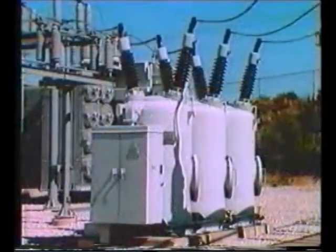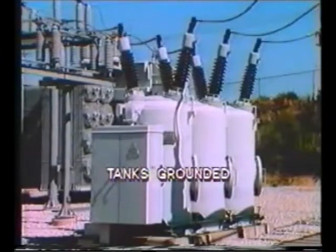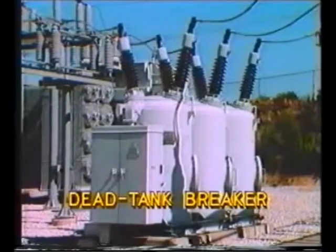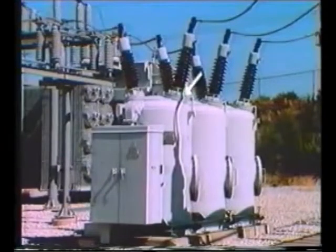The quenching medium may be oil, as in the case of this 132 kV oil circuit breaker. In this type of breaker, all three phases are immersed in oil tanks, and the tanks are grounded. This is known as a dead tank breaker. We mention it here because the item does have some significance in protection, as you'll see in later tapes. Incidentally, current transformers are usually located in the bushings here.